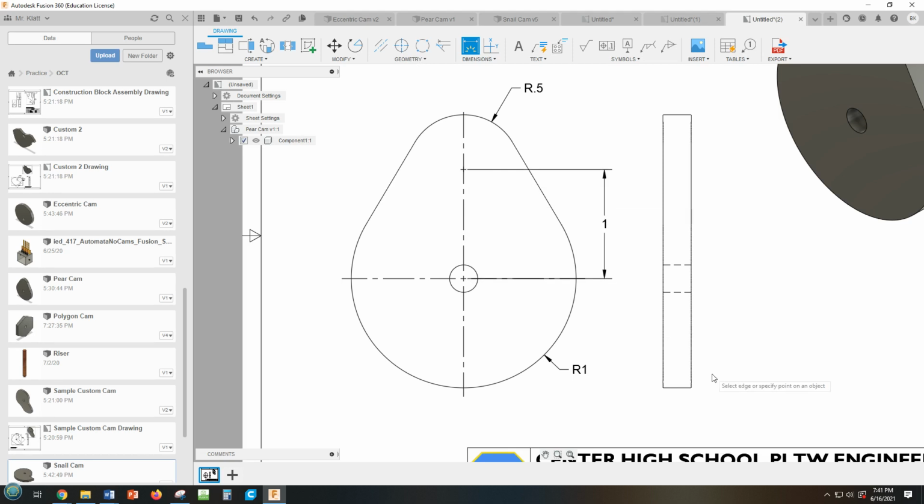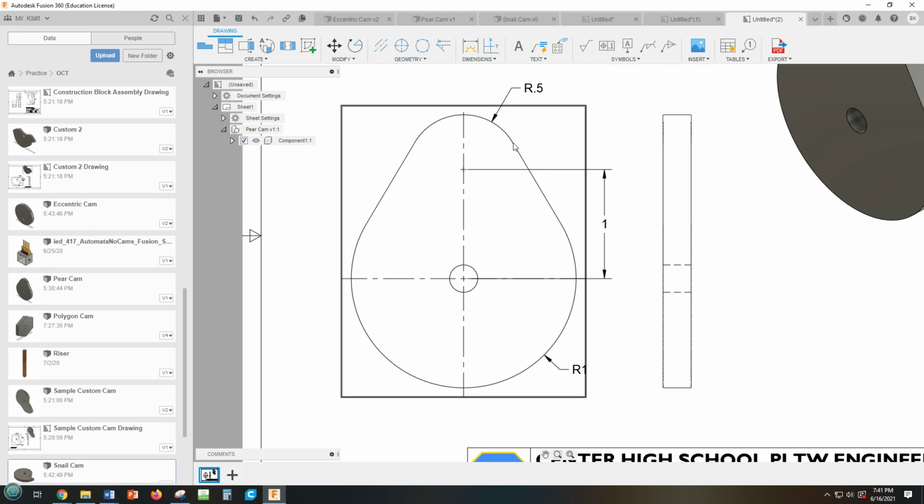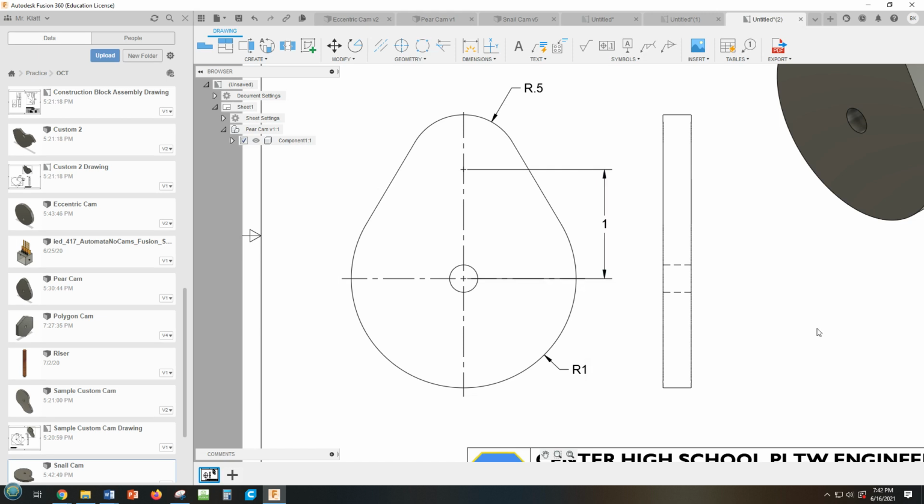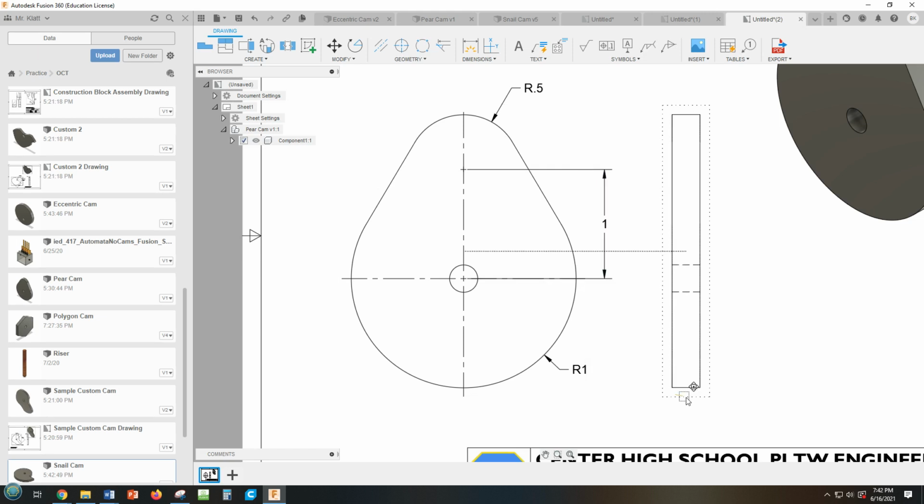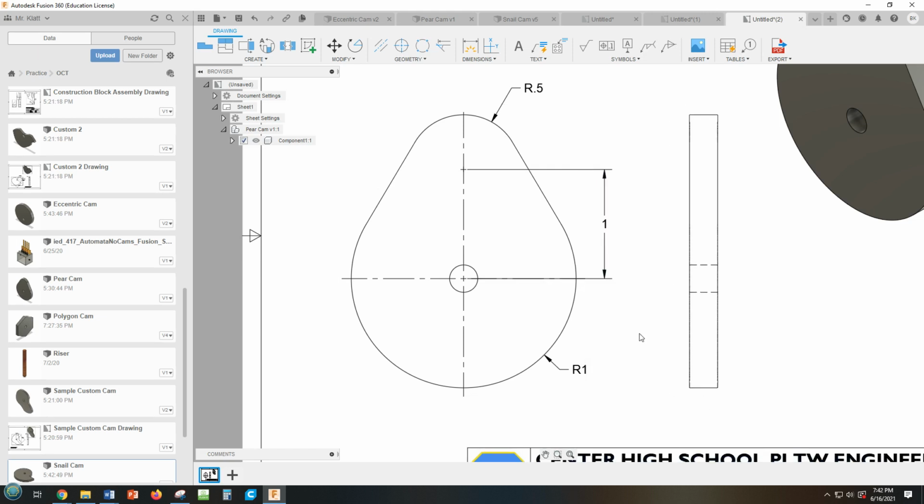Okay. Now we have in this drawing what's called implied points of tangency, and what that means is that where these lines meet appear to be tangent, so we can assume that they are. Those are implied. So this is actually okay. It's showing us where everything is.